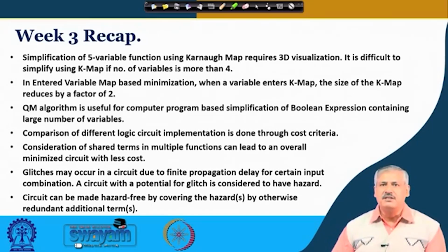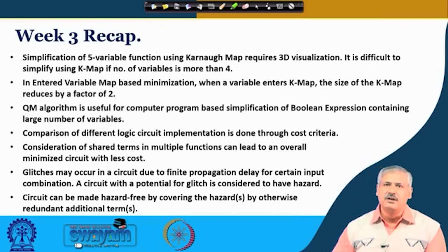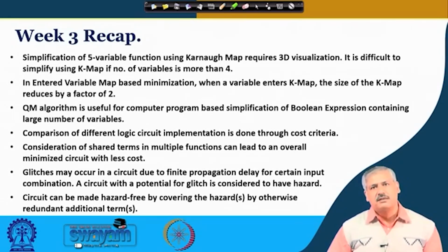And during realization, when we are doing the minimization, due to finite propagation delay, there could be glitches that can occur during the transition from one particular value to another, and such potential glitch in a circuit gives rise to hazard, and to cover hazard we need to include additional terms which are considered otherwise redundant. So this is briefly what we discussed in the last week.